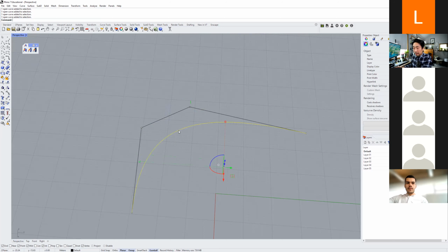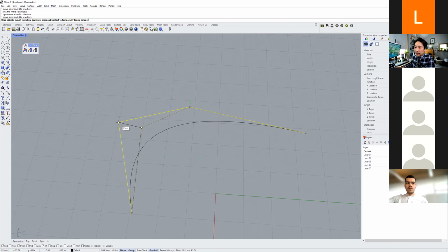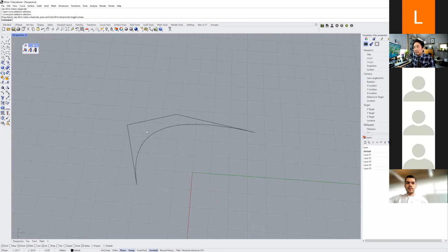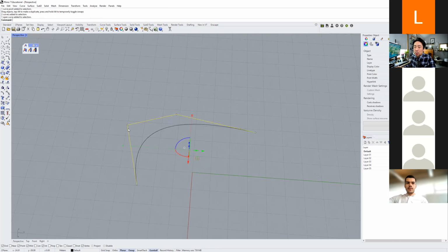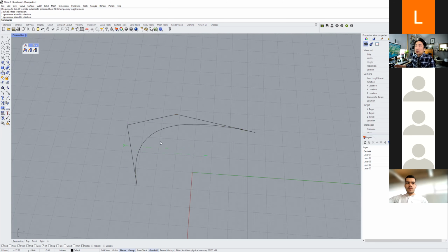So if I click this curve and press F10, I'm manipulating this object, right? Sub-D surface allows you to basically switch between something that's rectangular and something that's curved. So in a way, it's the best of both worlds, because you can go back to the mesh modeling mentality.